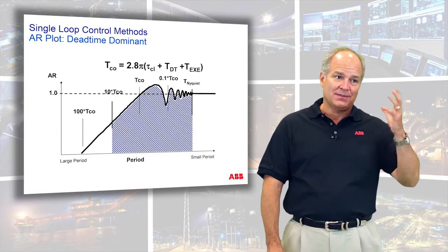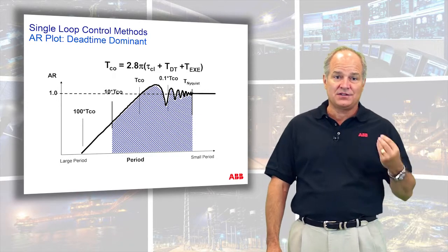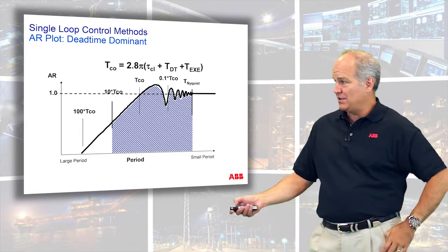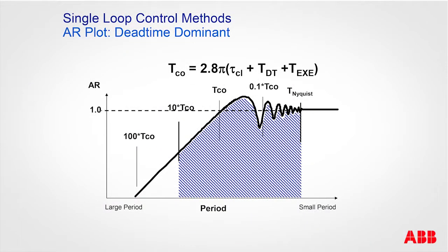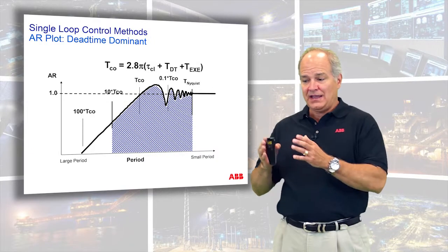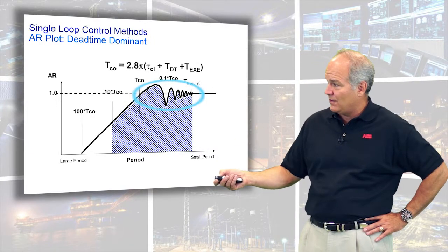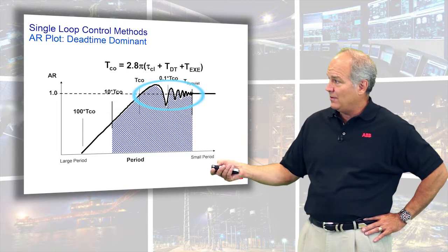Now, this is what's called a Bode plot, and we're not going to spend a lot of time on Bode plots. We talked about that when we talked about cyclic energy. In that discussion, we had a simple first order response where we attenuate frequencies over here and pass frequencies over here. Whenever dead time enters the process, you produce an amplification pattern. So you can see here that from the cutoff over we can attenuate, but then we amplify.